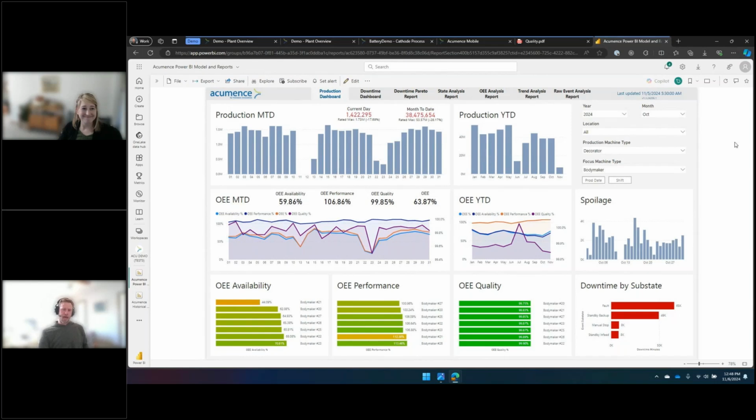You can look at a particular piece of tooling in a body maker, and if we're collecting the right data at the shop floor, like stroke counts, we can start to get an idea of, at X number of stroke counts, we're starting to see a lot more of these particular defects.